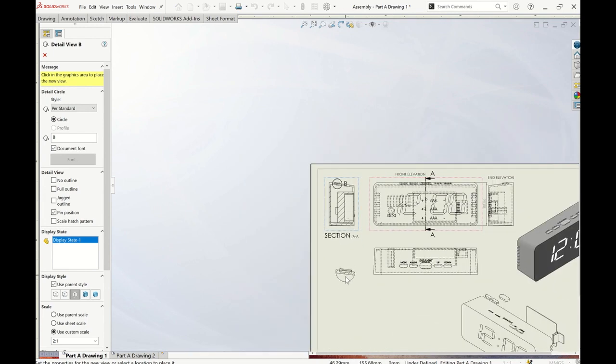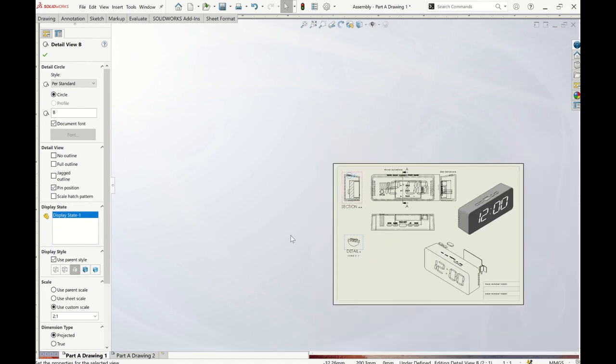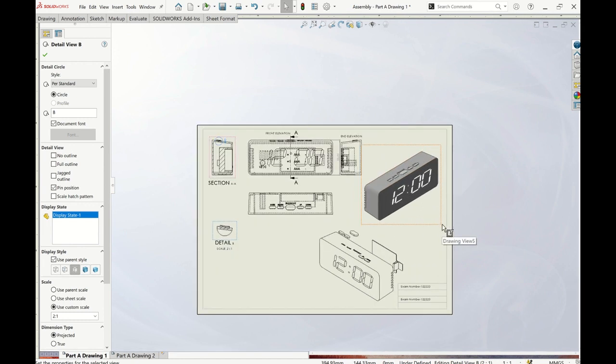It'll zoom it into a bigger profile, and I can move it down to the bottom of the page, and it'll label it there detail B, and B is up at the top there. You might need to move the B so it's not cutting over the project. That's most of it. You need to fill up your sheet. Don't leave any white space. So you might put different arrows and text there to fill it up. Your detail view could be bigger.